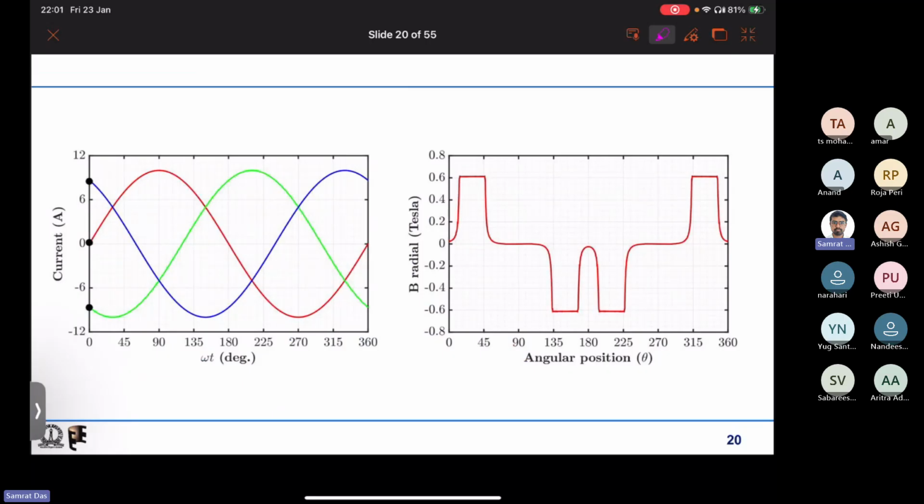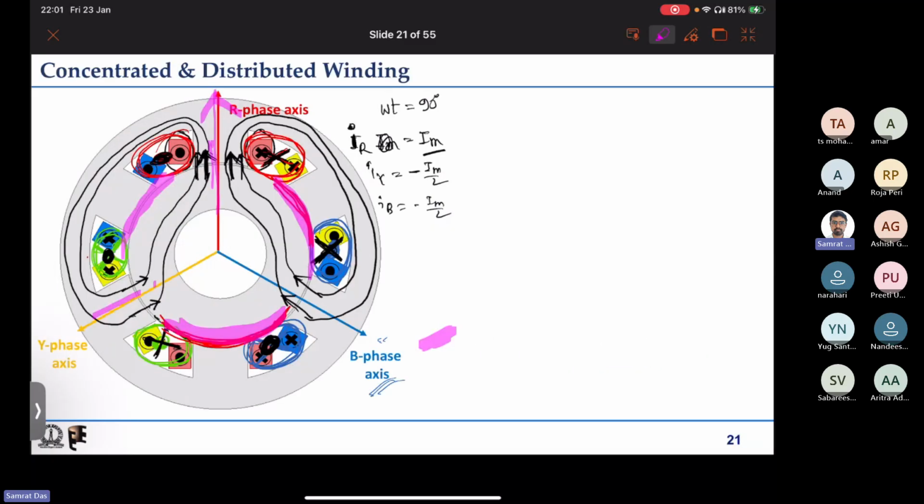But in this case, you can look at the waveform and clearly see that there is half-wave symmetry. If there is half-wave symmetry, then we can only have odd harmonics. We cannot have even harmonics. So yeah, thanks for pointing that out.